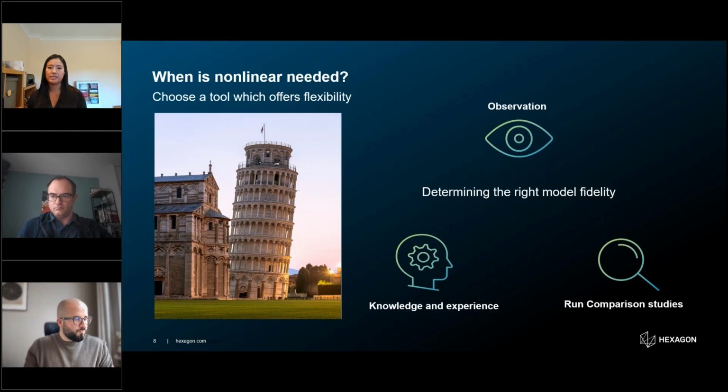Determining when nonlinear analysis is needed can be challenging. It involves balancing accuracy and problem size. But how do we know what to include and how much to include? Is a linear analysis sufficient? Quite often, simply by observing, you might see apparent behavior not being reflected in the simulation model. You could notice it by comparing simulation results with experimental data, and there's a mismatch. In some cases, unexpected prototype failure can happen during testing, and that's when you have the indication that a nonlinear analysis is required.